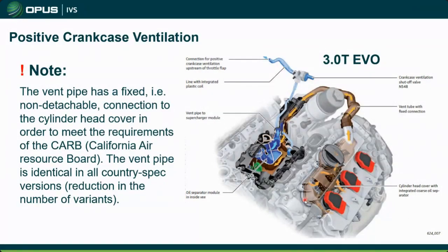My other suggestion is that if you guys are in the colder climates, you really don't want to touch this stuff if it's really cold, because all of these plastic pipes and everything get real brittle when they're cold. So just be aware of that. If you have to, let this thing warm up a little bit if you can before you start trying to pull these things apart, because the plastic doesn't do well with the real cold temperatures.